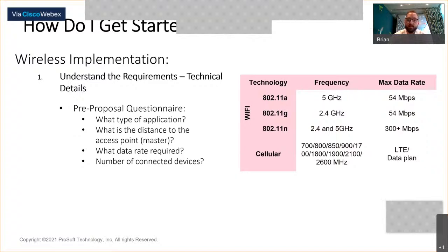That means limiting your broadcast packets and maximizing your unicast communications. In the typical control application, we recommend an overall packet rate of about 5,000 packets per second without aggregation. So with that number in mind, it's important to calculate the packet rates across all of the client devices going through a single access point to ensure the bandwidth of the overall wireless network meets the requirements of your application. In a dense application, it may be required to add an additional access point in that main control network.